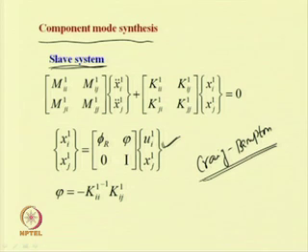The normal modes of the above system are found using eigenvalue analysis, and the physical coordinates of the slave system are transformed into a set of normal coordinates u and the degrees of freedom x j using the transformation. Here x j is the junction coordinate and u is the normal coordinates. So x i1 and x j1, where i is the interior degrees of freedom and j is the junction degrees of freedom, we are using for the slave part.